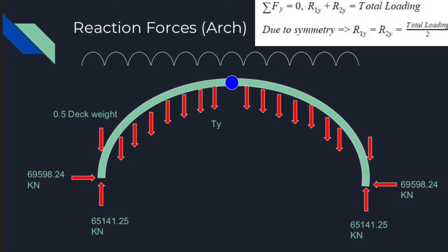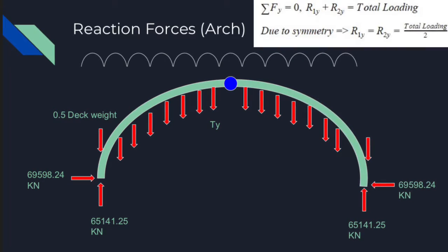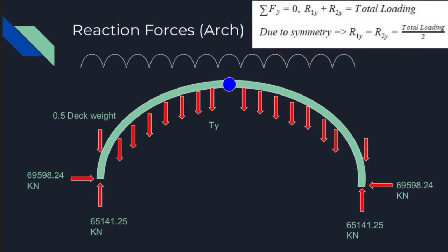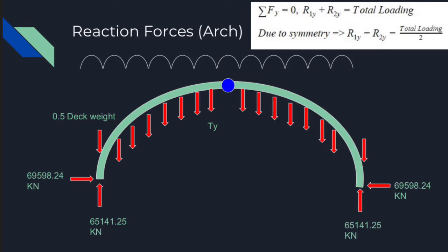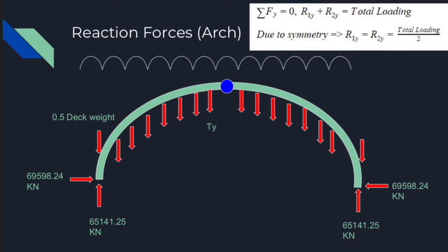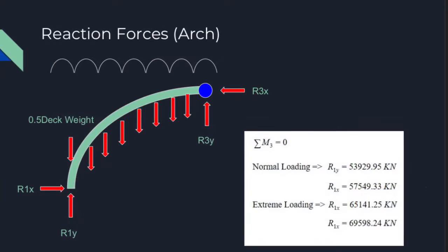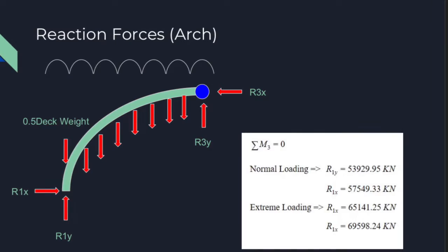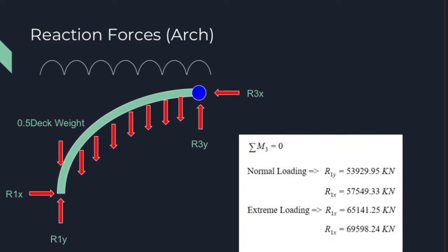The 2 major piers at the bottom of the arc are pinned and thus have x and y reactions. There is a distributed load on the top of the arch, which is the weight of the arch itself. We turn this value into a point load for our calculations. The red arrows pointing down from the arch are the tensile forces in the cables, which are all the same. As previously mentioned, there is a hinge at the center of the arc to represent 0 moment. We then made a cut at the hinge and took the sum of the moments at that point, which gave us the x reaction value for the major pier. From there, it was statics.